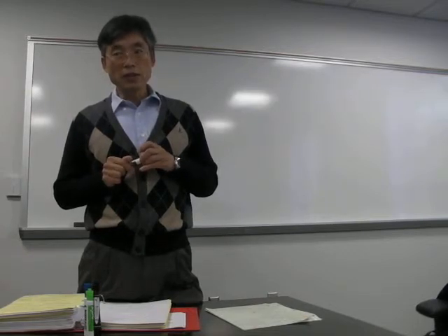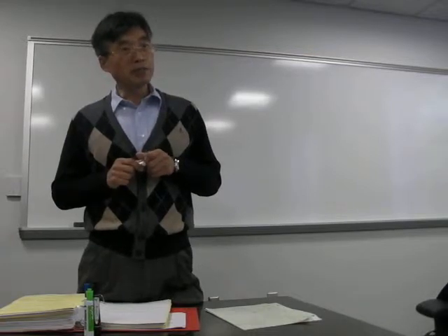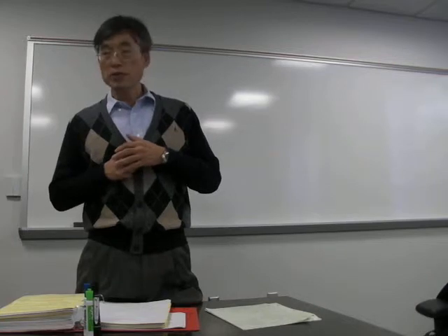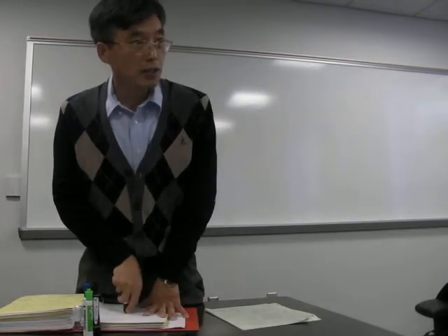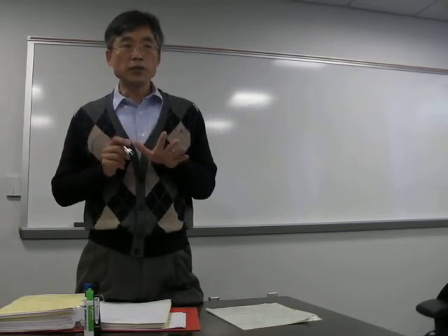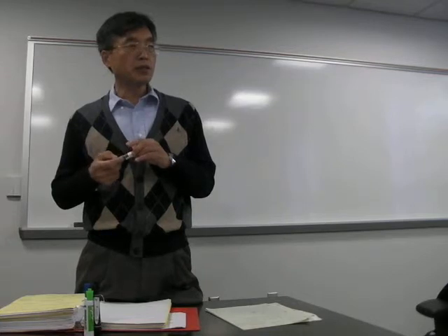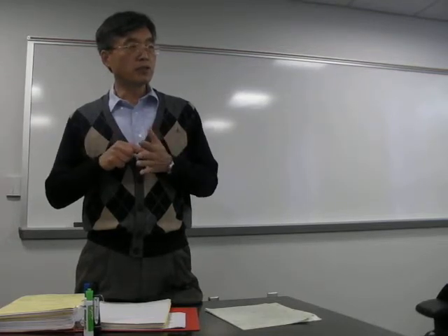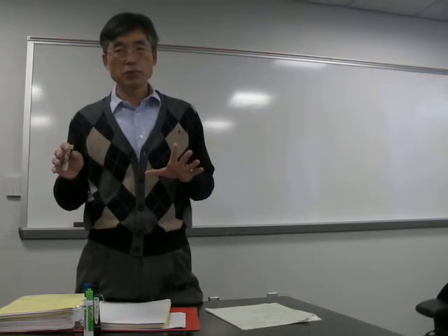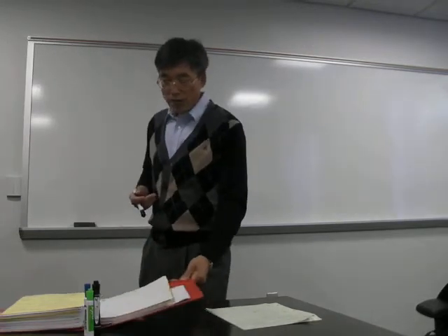You can knock on Dr. Mullen's door and ask him, what is the earthquake design acceleration in the Oxford area? Depending on which area you are in, design acceleration will be different. I recall the design acceleration for earthquake somewhere in here should be 0.170 or somewhere around there. In California, it may be higher. Okay? And today,